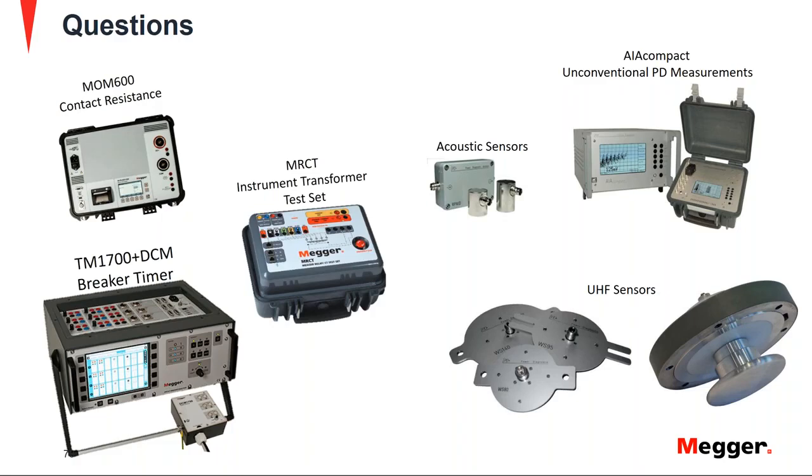Thank you, Volney. Next to Daniel, can I measure close open and open close open operations using DCM? Thank you, Marco. Yes, you sure can. As Volney just explained, DCM is a technology that can be used in a wide range of applications. And yes, as the name implies, it's a dynamic measurement. So just as with conventional timing, when you set up your circuit breaker analyzer, you define, okay, my length of measurement is 1 second or 100 milliseconds, whatever you decide for a particular operation, and that includes the combined operations like the close open and open close open. So yes, DCM will work for those as well. It will be just as accurate as with the single operation.